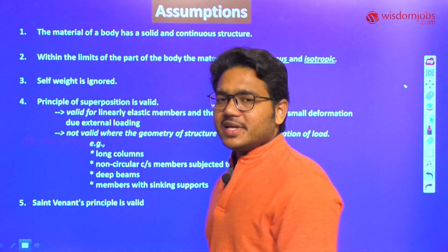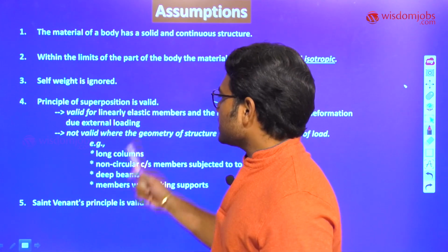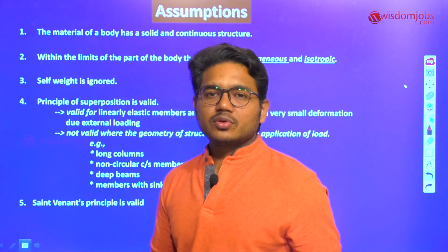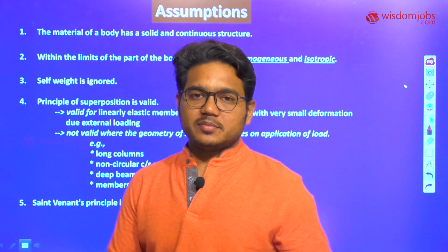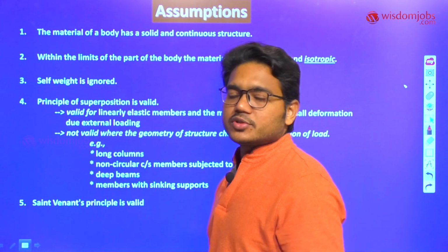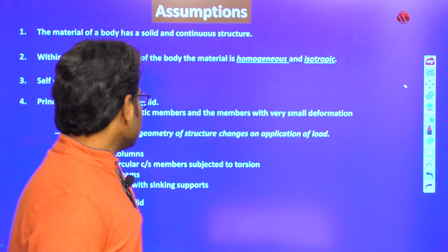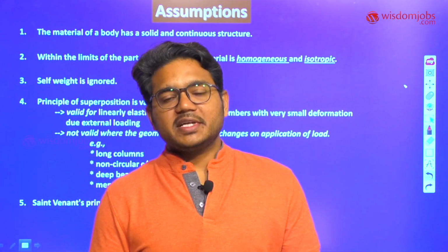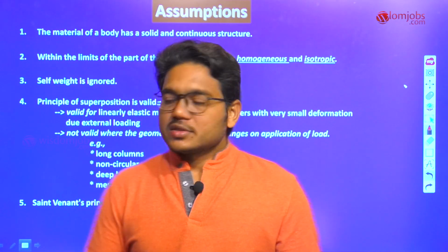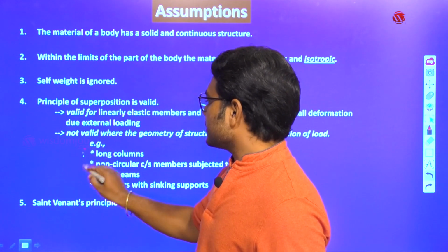Here the principle of superposition is valid. It is valid for linearly elastic members, that is, only members subjected to loading up to their elastic limit. Up to that point we will be using the principle of superposition. And it is not valid in some cases, where the external loads tend to change the geometry of that particular member.